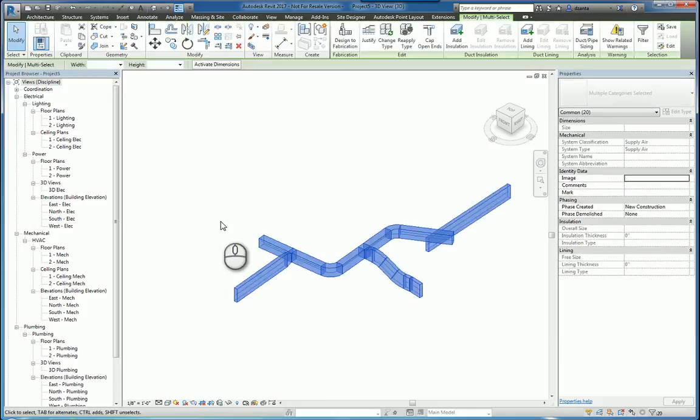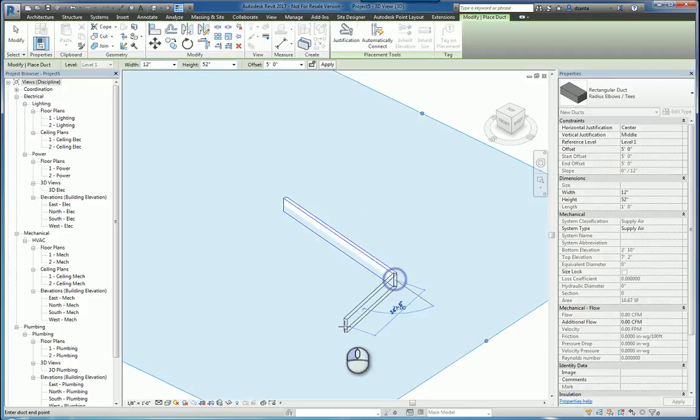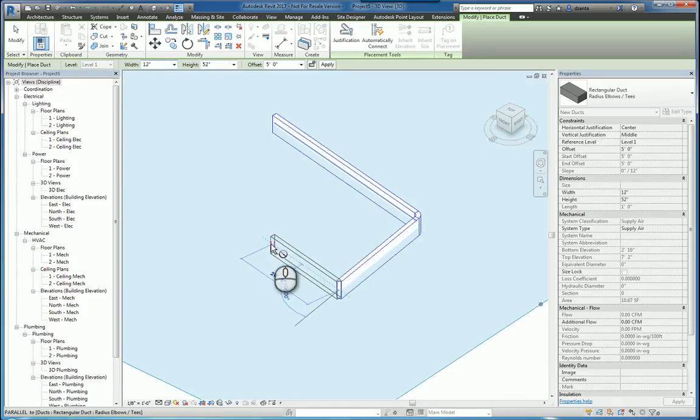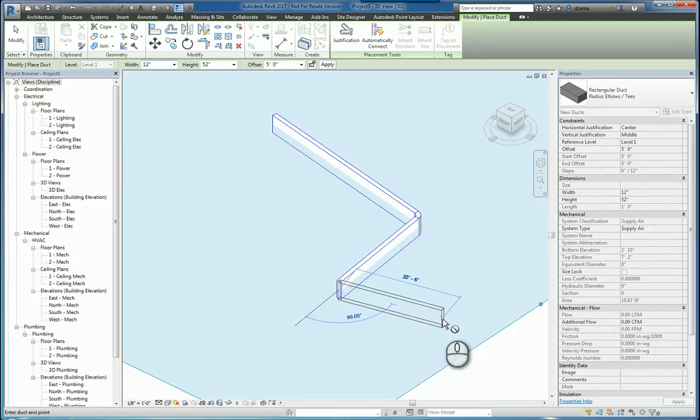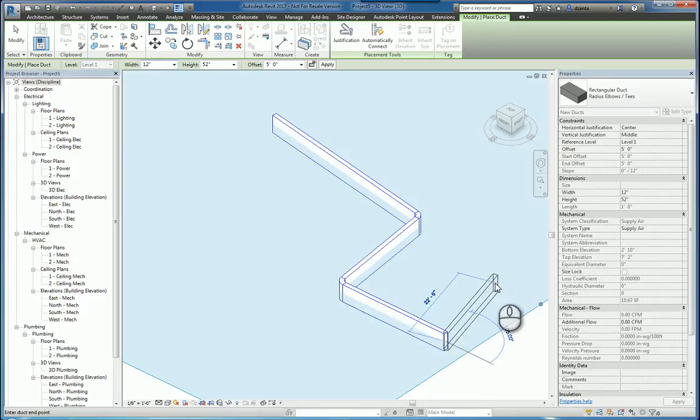Let's go ahead and erase this again and draw some ductwork. Also, by the way, when you're drawing ductwork, piping, or cable tray, and you're trying to place it like I'm doing here, and there's a circle with a diagonal across it next to your cursor, what that means is that you're trying to draw it at such an angle where the default fittings that have been set up for that system won't work. So as you can see, it won't let me do it. However, if I'm drawing it and I don't get the circle on the diagonal, I can draw that object.